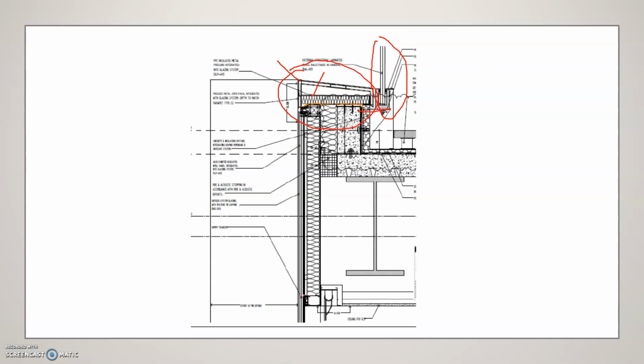If you notice this element here, normally you go curtain walling with a face cap, so it should be something like this. But on this one there is no face cap, which means the curtain walling system the architect is trying to use is the SSG, the structurally glazed curtain walling. From the outside they'll have to put some sort of siliconing instead of the face cap.